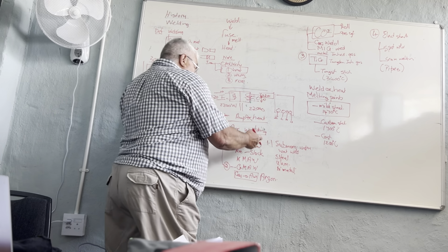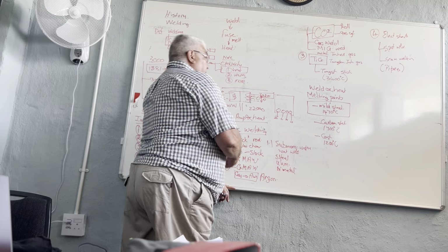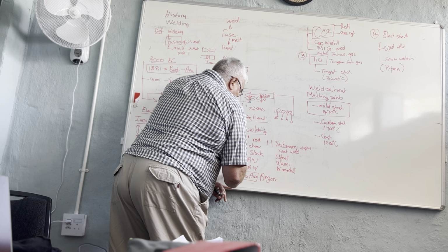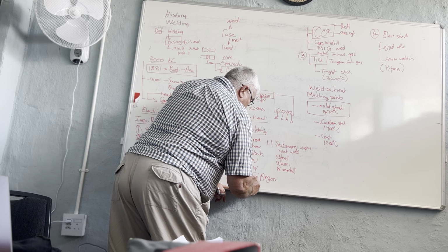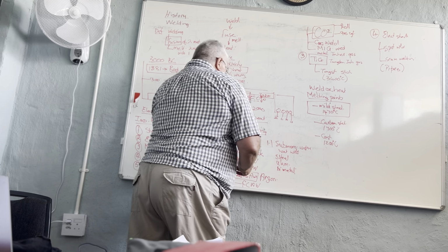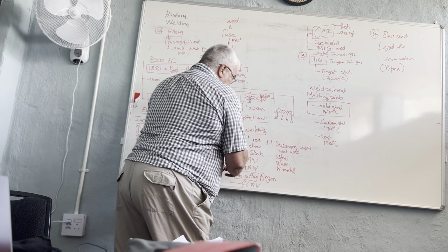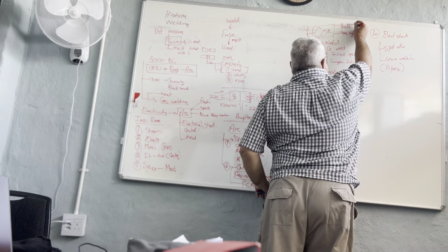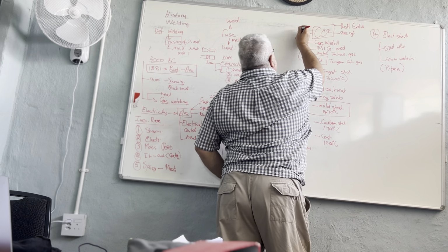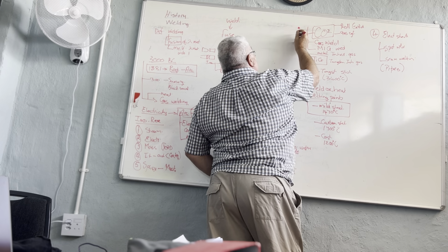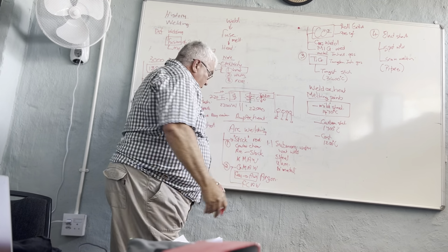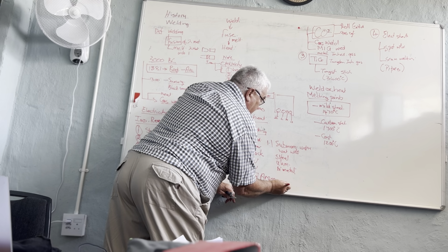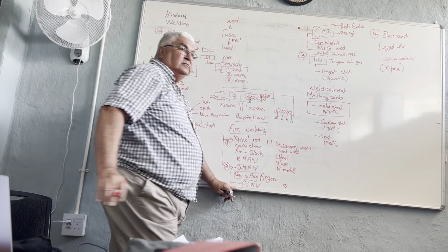But in each process, like in gas, with the argon, now I'm getting mixes in argon, and what we can do in this one is put flux core arc welding. Now what this means is, the gas metal arc welding uses a roll of wire, solid. This is solid. So if I look at that rod, it's a solid wire rod from the front. Flux core has taken the gas away in some cases, and the flux is included inside the wire.